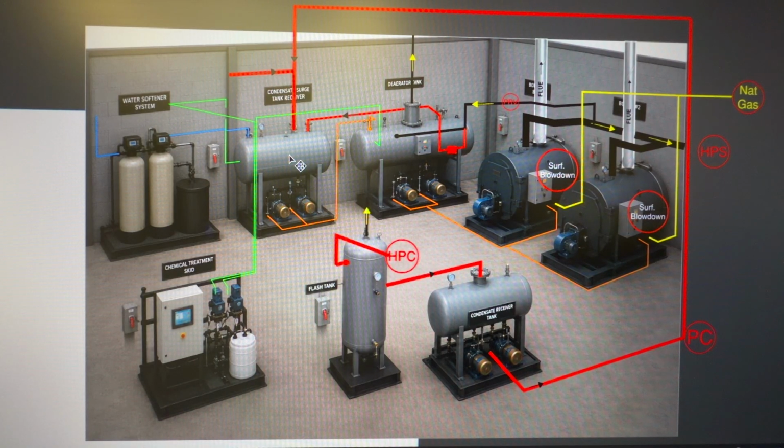The purpose of it is to collect returning condensate, recover heat in treated water, prevent pump short cycling, and maintain a consistent water supply to the deaerator.